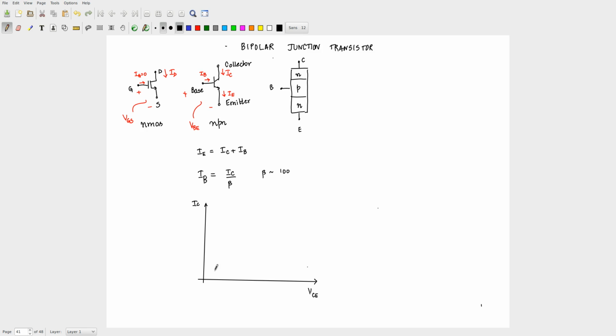All of your digital electronics is enabled by MOS, and because of that many circuit designers want to make analog circuits also with MOS, so that you can have a single silicon wafer on which you can have both analog and digital circuits, which is what your phone is, for example, right? You need to have amplifier blocks and filters and all of that, those are all analog.